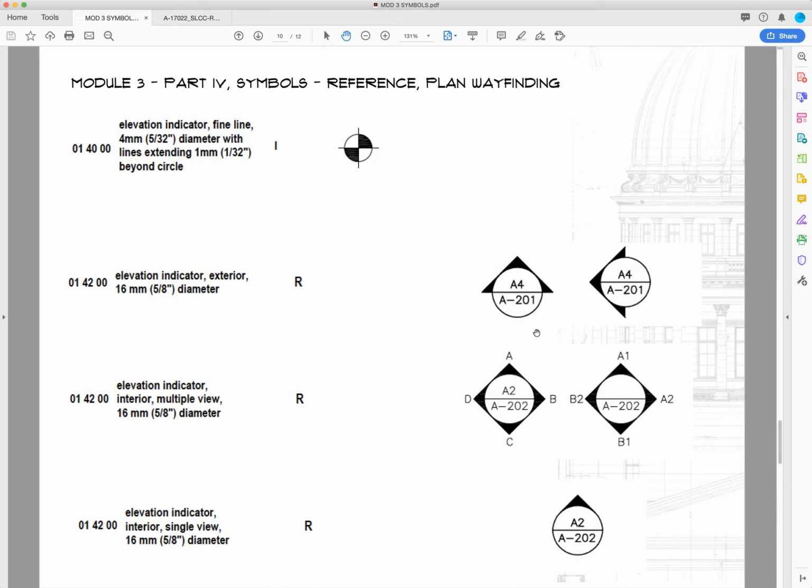So you can see the graphic difference between having one interior elevation versus all four called out. And again, these are typically found in your plan views, and then it takes you to your other sheets. Here you can see that it's calling out to the 200s for the exterior elevations, and with the interiors they're also showing it as the enlarged plans, but these are also commonly found on the 400 sheets as well.